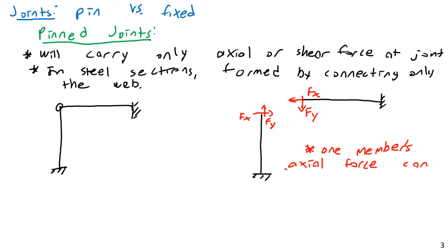It can become another's shear in certain cases. So think about that. Think about the end shear, actually. It'd be the end shear, and then it would end up being basically an end force there. So that would be the starting point of the shear diagram. For example, this Fy, for the column here, is an axial force. But when it enters the beam here on the left end, that is going to be the starting value of the shear diagram.